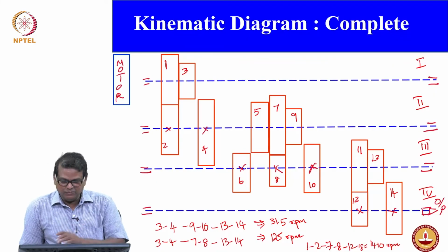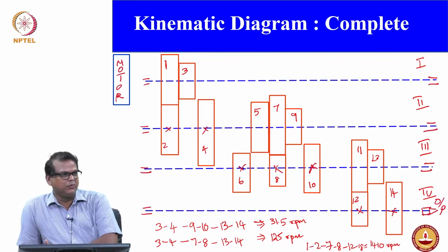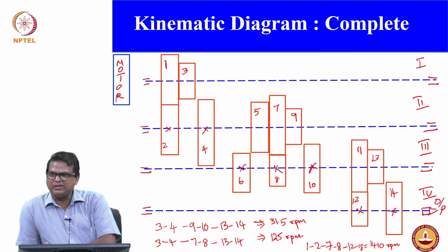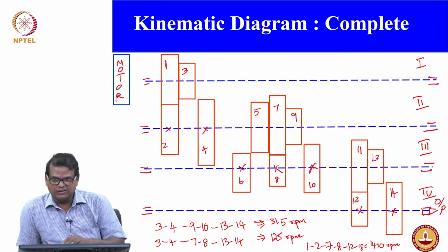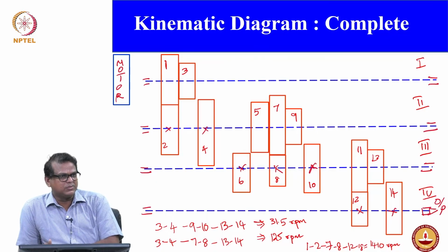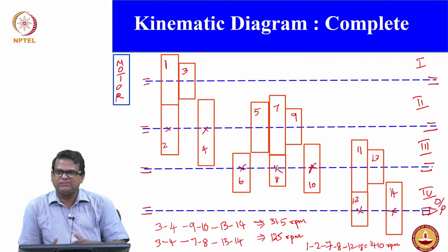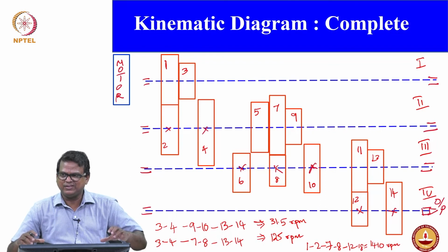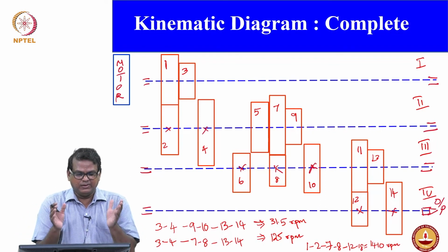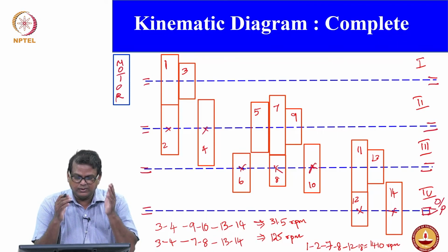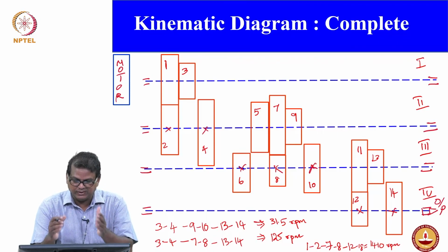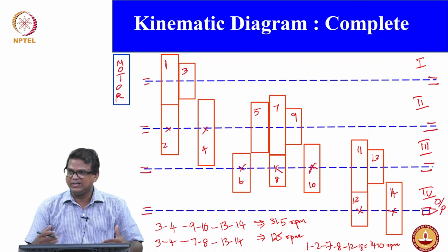Okay. So now the next thing we are going to focus on is the number of teeth aspect. Okay. So number of teeth, we need to find out for each gear. Of course, you can approach in 2 ways. Generally, as I said at the beginning of the lecture, we will use the center distance, right. So assuming that for gears 1 and 3, 2, 4, 5, 7, 9, they should have the same center distance, otherwise it's not possible.